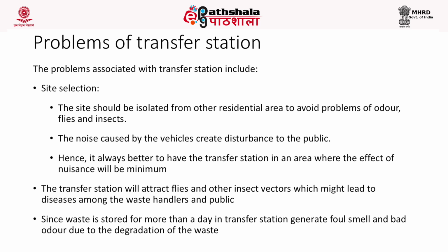nuisances can be avoided. The transfer station will attract flies and other insect vectors which can cause a lot of diseases among the public. Since the waste is going to be stored for more than a day in a transfer station, it generates a lot of foul smell and bad odor due to the decomposition of the waste.